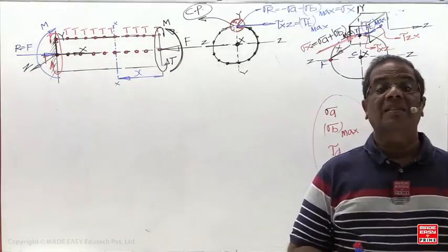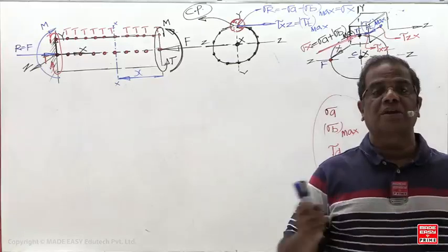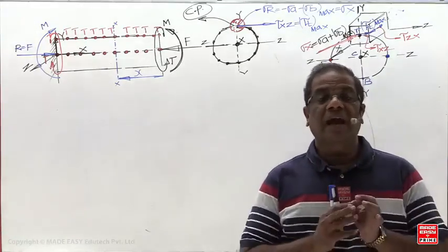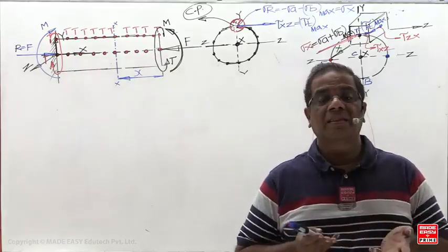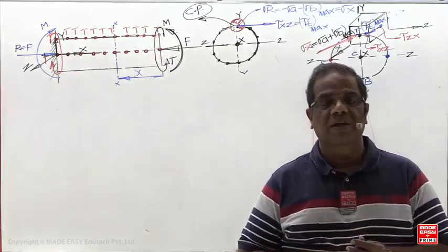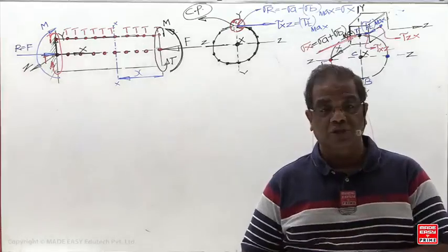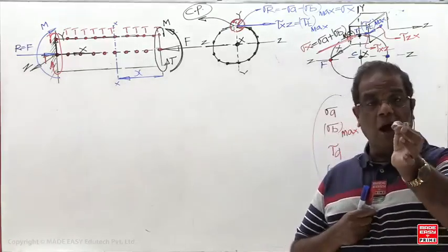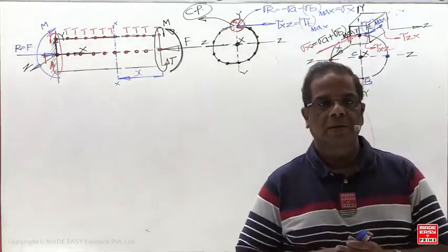Everybody is going to ask what the axial longitudinal fiber means. It is the longitudinal axis. Imagine a line joining the centroids of each and every cross section. At the centroid, bending stress is 0 and torsional shear is 0. So for this given question, option D is correct.